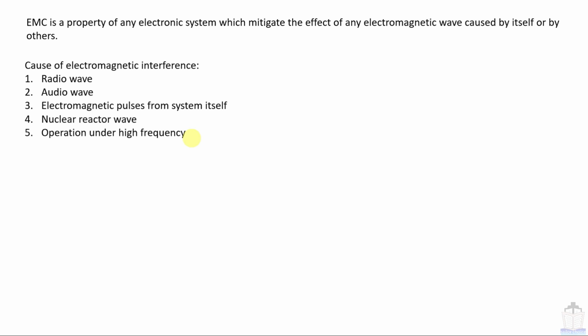If a conductor is carrying very high frequency, then unwanted electromagnetic waves are generated and they can hinder the operation of some PLCs. Okay. What are the remedies? The remedy is EMC circuit design. EMC circuit design means conductors which are carrying high frequency, you have to isolate those.